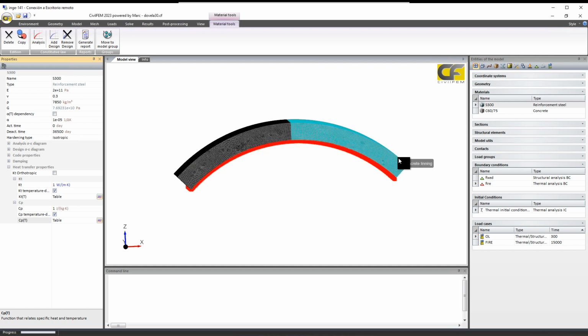So with this basic model, we have applied different boundary conditions. The first was simply supported at both ends, so at this end it could have displacements and also rotation. Another boundary condition was to fix the radial deformation, so this block could not have displacement in the circumferential direction, but we released the radial direction, so the radial direction was free but not the circumferential.